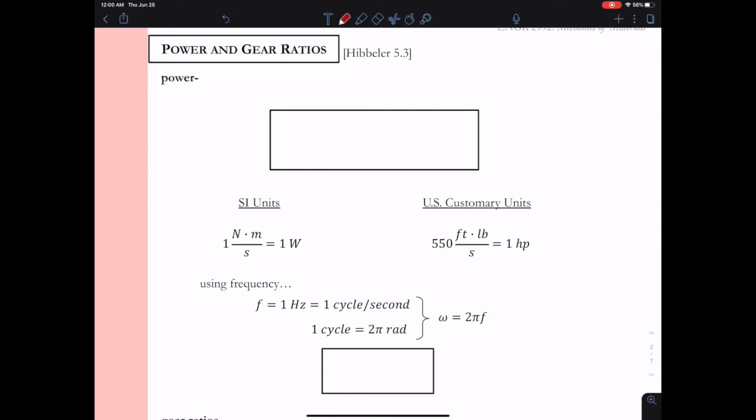As engineers, we define power as the work per unit time. And if we remember from our physics or science class, work is equal to a force times a distance. So when we talk about power in terms of this spinning system, this gear shaft that's spinning, our power will then be the torque as our force, and then we have to multiply it by our distance.